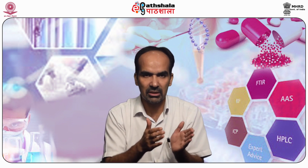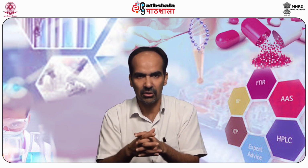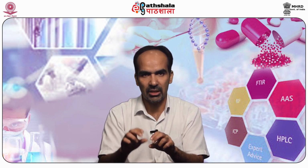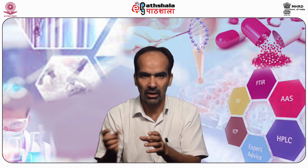It can be a simple steam distillation where the plant material is put along with water in a distillation flask, which is fitted with a condenser, and the contents are heated. The steam along with the oil distills off and is collected in the receiver. Because the volatile oil and water separate into two immiscible liquids, the oil can be removed and obtained in the form of an oil.